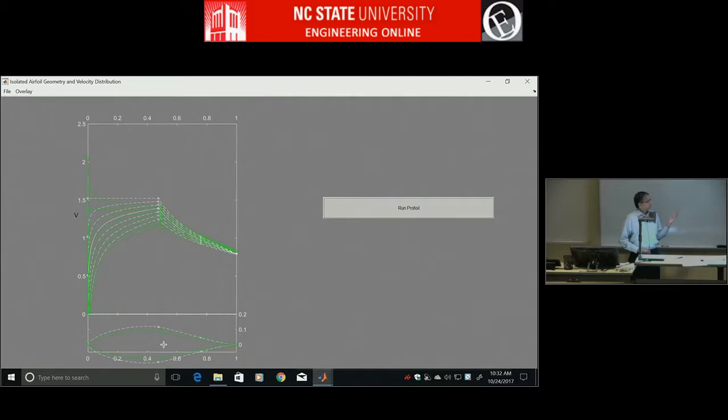So one way to control thickness is to vary the alpha star, right? There are times when you have to design an airfoil of a certain thickness. Many times that happens, right? You usually have a thickness constraint, and somebody will say design a 12% airfoil, and you have to do it. So in this method, the way to achieve thickness is to vary the alpha star too. At one point you have to give up on something. If you have to get the thickness, you may have to give up on exactly what you want in aerodynamics and you get thickness.